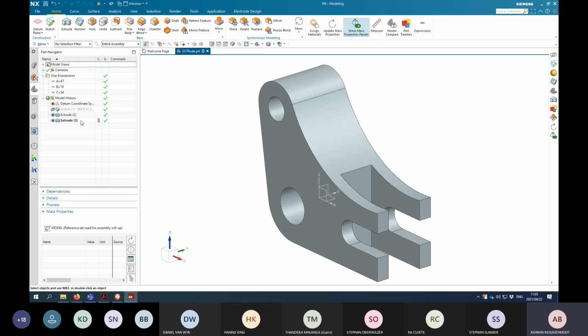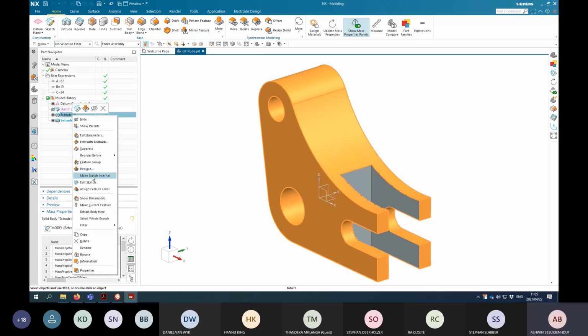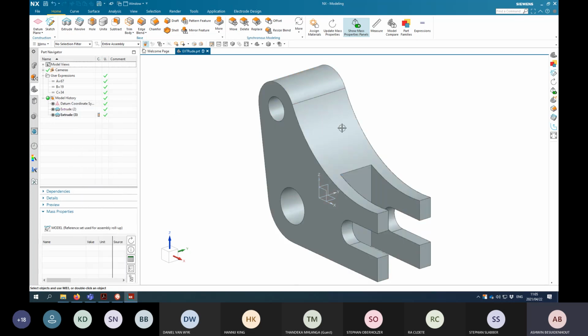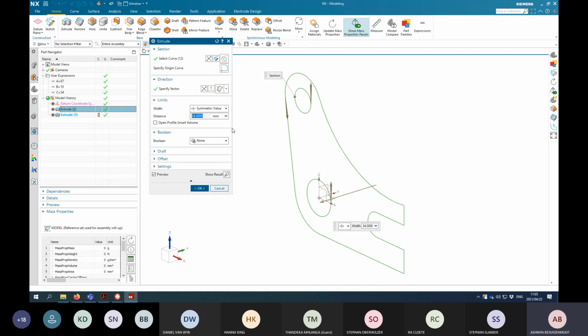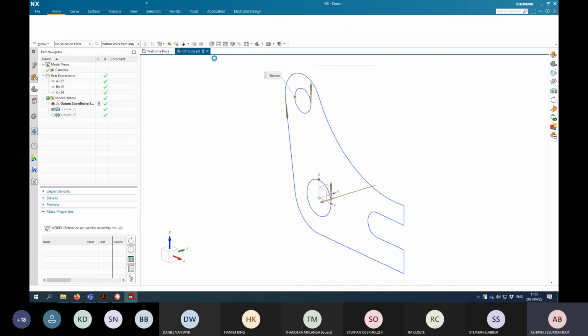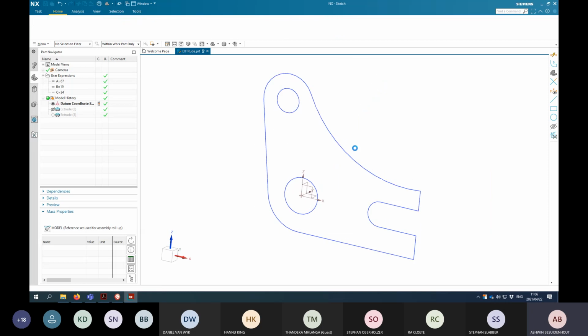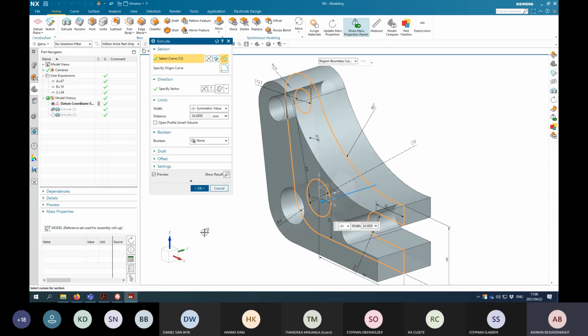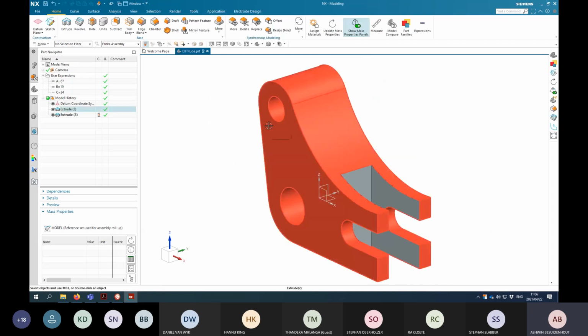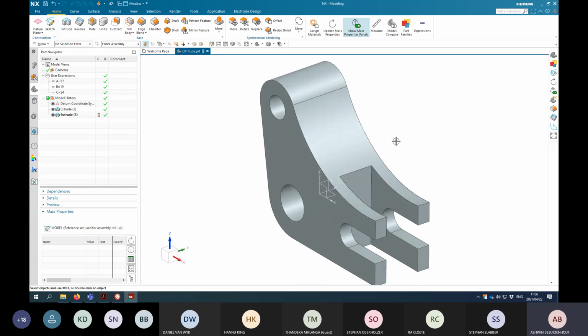You can actually do this as well. But the problem with doing this is that whenever you need to make a change on the part, you'll have to go into the sketch and get access to the sketch. So that's a long way to do it, but I know that it will be fine. All of the dimensions have changed. It's not within the sketch, it's in the user expression. So having my sketch fully constrained makes it a lot easier.